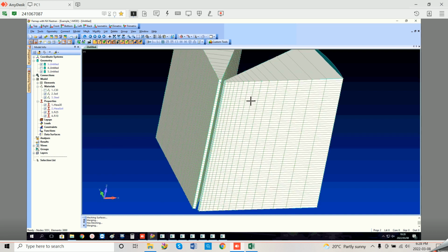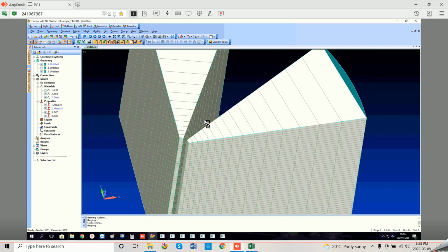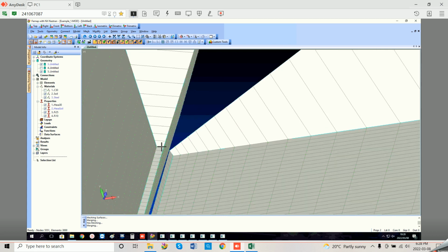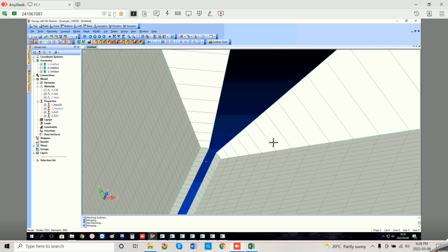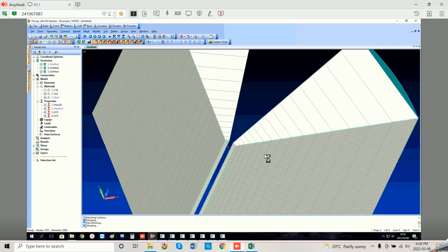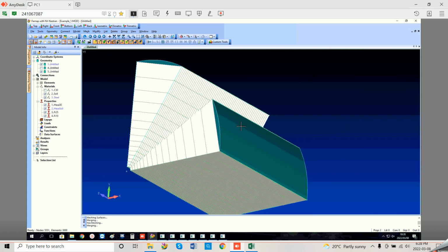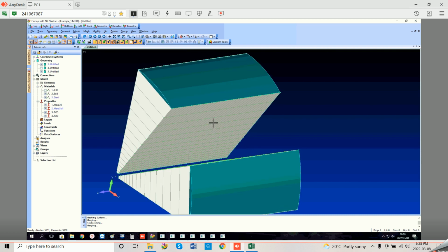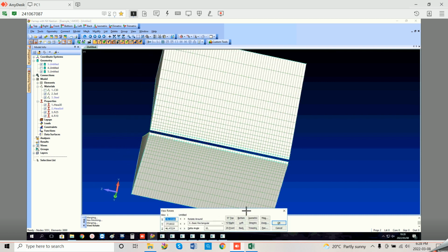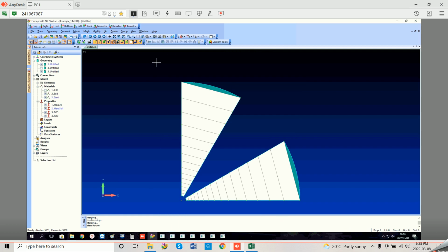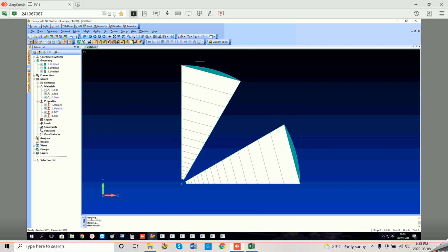And there it is meshed. Now you can see that it has created our elements where the small elements are closer to the pile, and there are elements on the bottom as well. We will delete the geometry just now, so we won't need the geometry later.